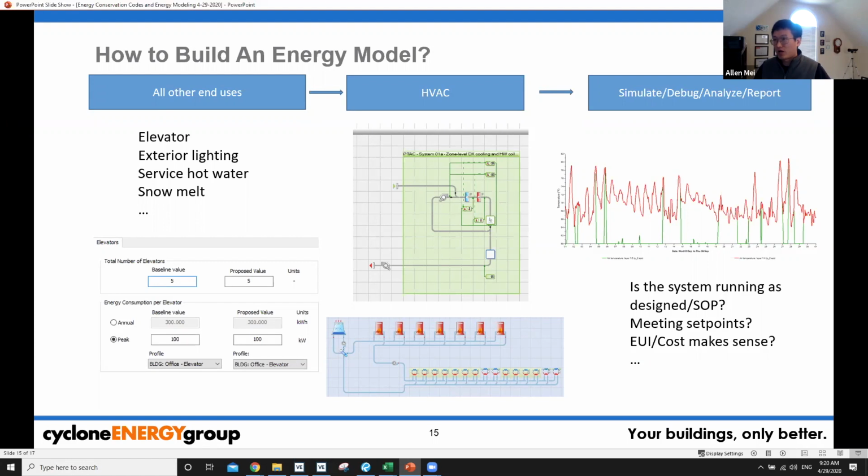Here you grab the information from the mechanical drawings, right? How big is your fan? Do you have a VFD on them? How big is your cooling coil? What type of cooling coil? How big is your heating coil? Do you have cooling towers? Do you have boilers? Do you have a chiller? Things like that. But actually, those are easy to input. I mean, if I have a 40 brake horsepower fan, I just put 40 brake horsepower. But the difficult part is the control.